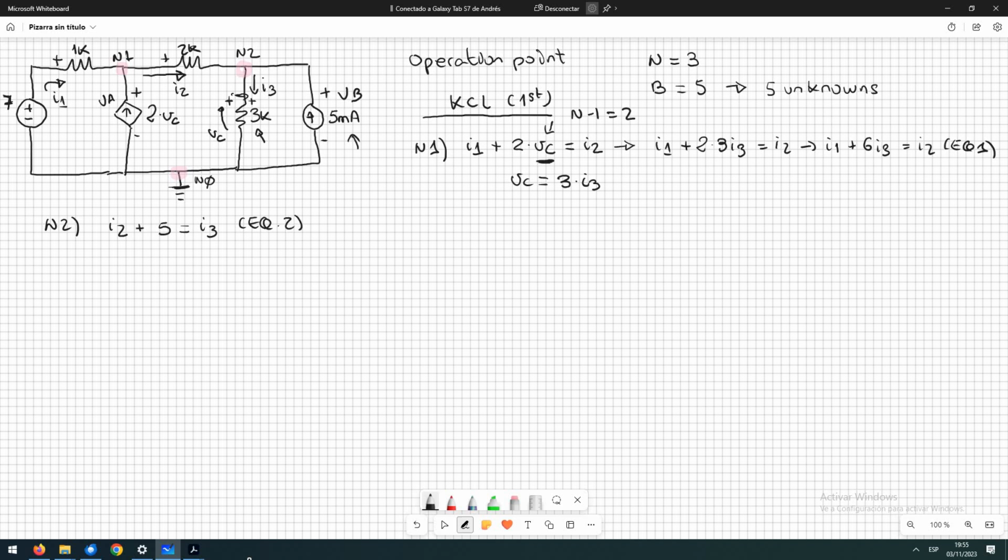So now we are going to apply the Kirchhoff voltage law, or the second Kirchhoff law, that of the voltages, that of the loops, and we have to apply this law to the number of branches minus the number of nodes minus 1. That is going to be these 3 loops that we can choose. I always recommend to choose the loop formed by each square of the circuit. It's going to be simpler. Remember to use a clockwise direction.